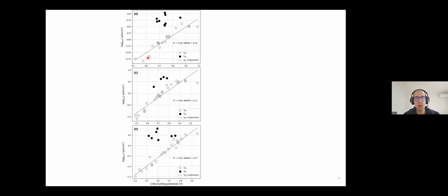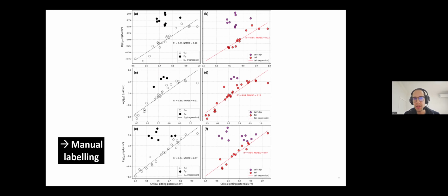In case one of the pitting pathway, it's pretty much a linear relation. And the other one escapes this pattern and is potentially more dangerous, as you can see. But once we have manual labeling, we can compare, of course, to what our unsupervised approach suggested to us. And the correspondence between those two populations was not perfect. If this was a classifier, it would not have been perfect, but it was quite accurate. So we could finally think of using these two as a machine learning predictive tool and deploy this machine to find in an unsupervised fashion potentially the most critical pitting pathways out of polarization curves.